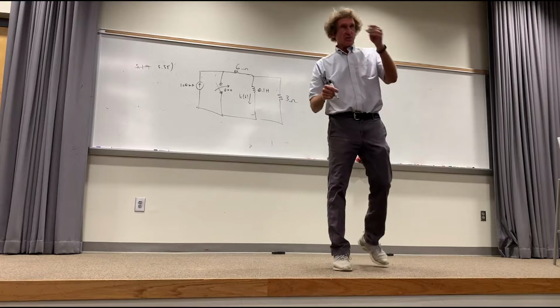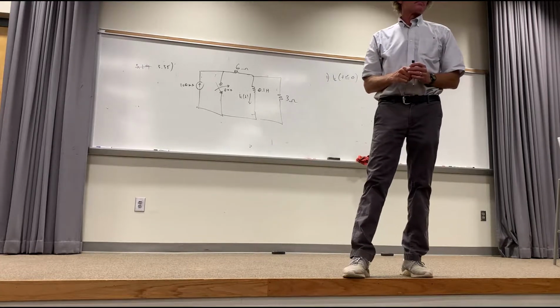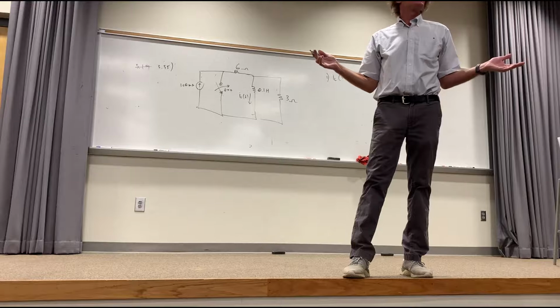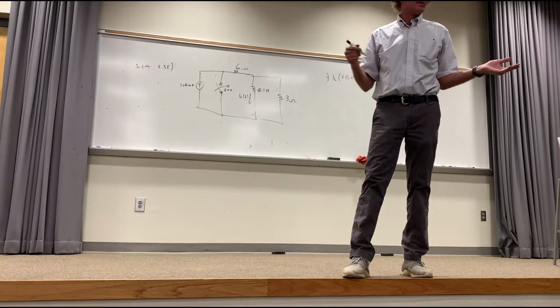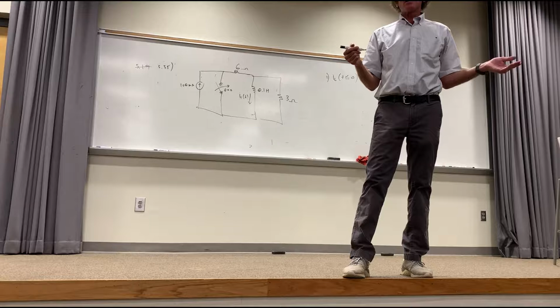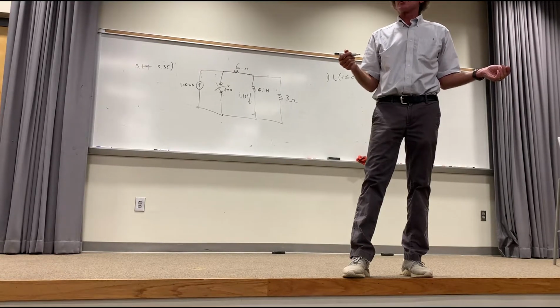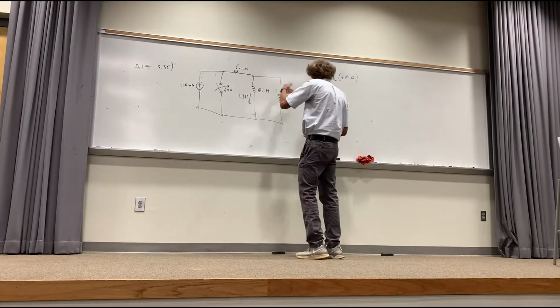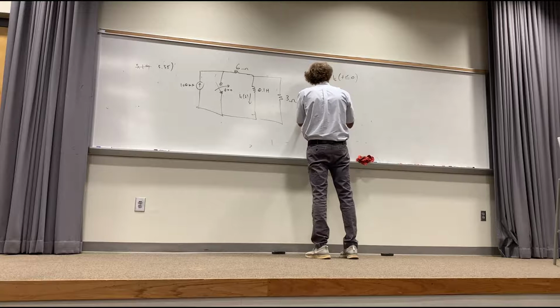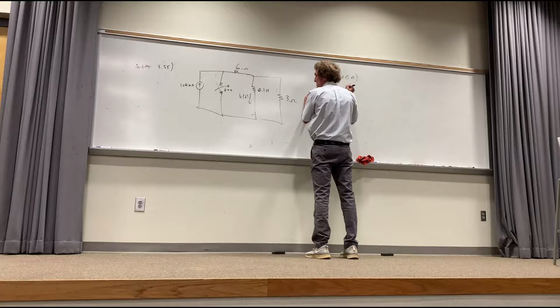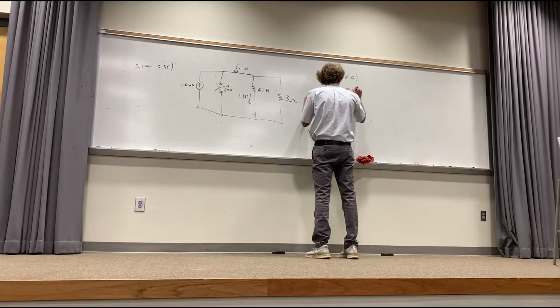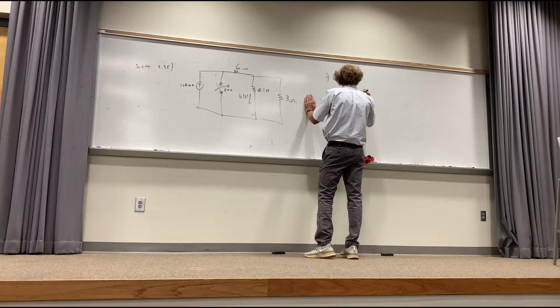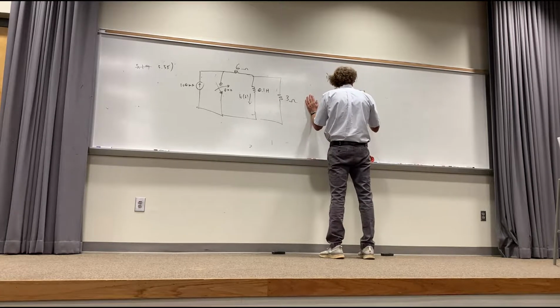Now, what does an inductor look like for t less than or equal to 0? It looks like a straight wire. The reason is, it is a straight wire, just wound up, right? And now there's no time-varying magnetic field, so it is literally just a short circuit. So for t less than 0, the circuit actually looks like 100 milliamps, and then you have 6 ohms, and then you have just a short circuit, and this is IL here for t less than 0.